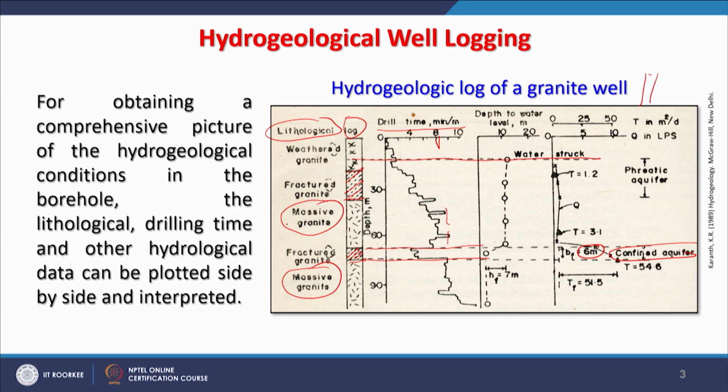Then another recording at the time of your boring or drilling is the depth to water level, at what time the water was encountered. So, here the water struck at this stage, and then see here it is the 10 meter, it is the 20 meter. So, initially it was struck, and then of course, you were getting water for most of the time in this well, maybe in this portion you are not having water, and then suddenly the water level reduces here.